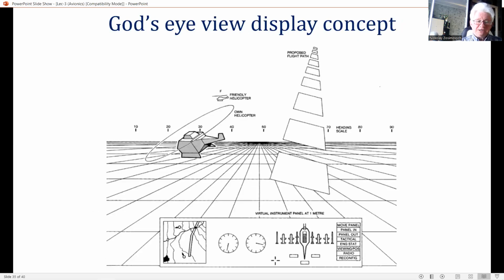Novel ways of presenting information to the pilot by means of the binocular HMD include displaying a 3D pathway in the sky as a flight-director display, which can be overlaid on the normal outside scene, directly or indirectly viewed, or on a computer-generated outside world scene created from a terrain database.